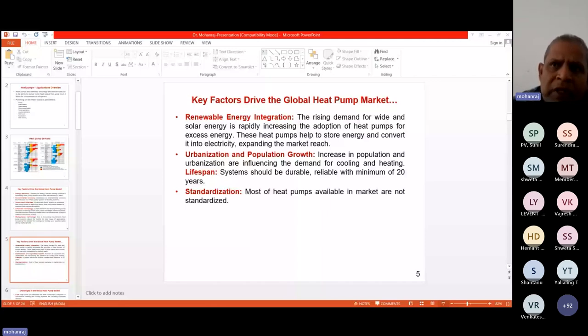These olefins have a lot of advantages with respect to operating temperature, critical properties, thermodynamic properties, and thermophysical characteristics. It's well and good, but the problem is this type of working fluid cannot be used according to the Paris Protocol 2016. Even though it has a low global warming potential, the fast decomposition of such working fluids in the atmosphere, an unsaturated hydrochlorofluorocarbon or unsaturated hydrofluorocarbon, creates a sudden impact on the environment, which is not good. So we will have to face these refrigerants also soon.